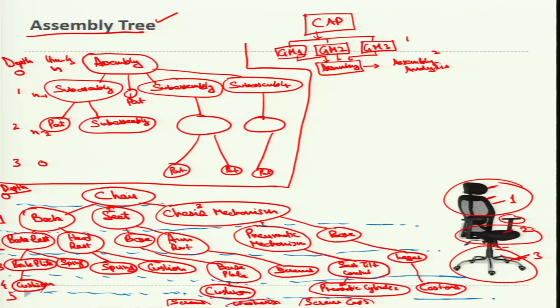So these changes matter when we talk about computer aided manufacturing. This kind of chair that I am showing is manufactured using plastic molding machines. Only the metal part would be manufactured on machines such as CNC, and the screws and bolts are majorly made by special purpose machines. Special purpose machines are machines used for mass production. For example, a bolt maker is a machine in which you put the billet, a round piece, as the input. It first transforms that round piece into a hexagonal shape, which is metal forming, then cuts it, then does machining operations over it, and makes the bolt of the size that you require. This is a special purpose machine.